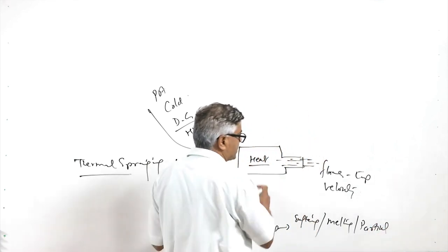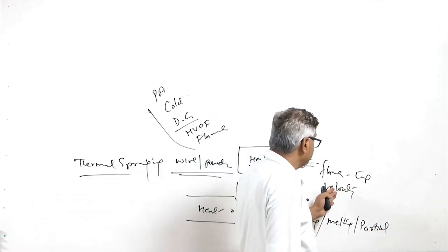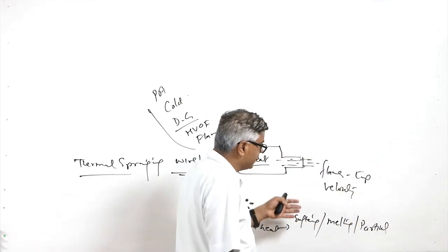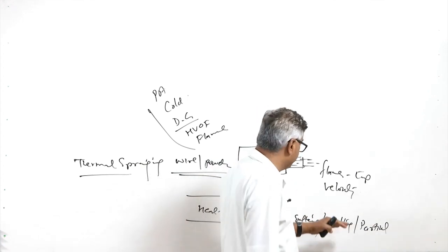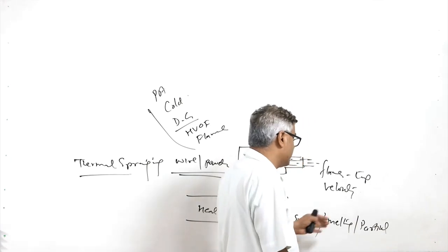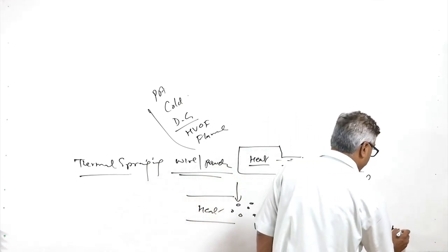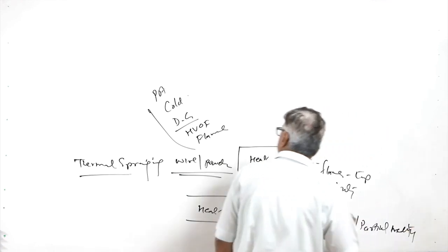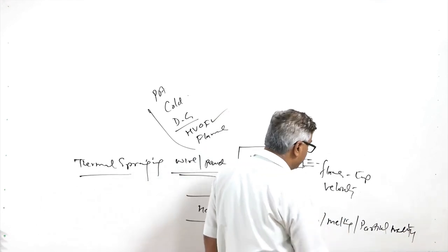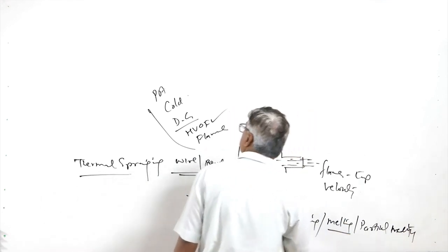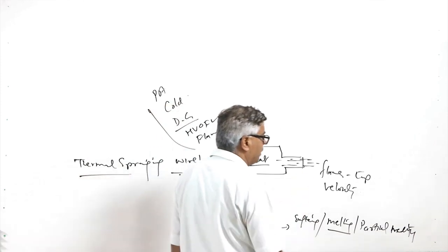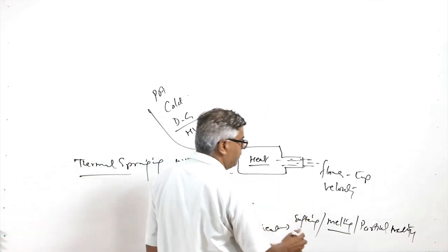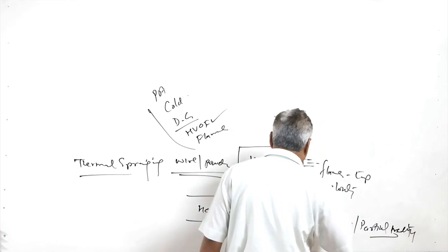Depending upon the process, the velocity achieved and the temperature attained, the different processes will lead to different conditions of the material being deposited, like either complete melting, or partial melting, or just softening. For example, in the high velocity oxy-fuel process, the HVOF process, there is just softening, no melting, but the melting takes place in the flame spray process, like the low velocity flame spray process. So in detonation gun and high velocity oxy-fuel processes, mainly either partial melting or just softening takes place.